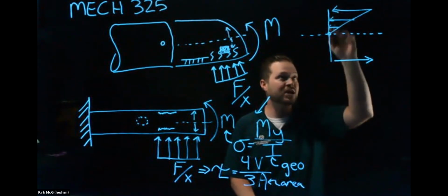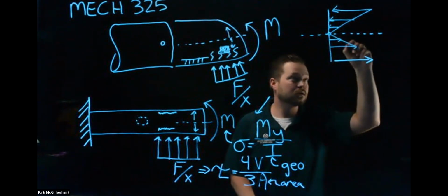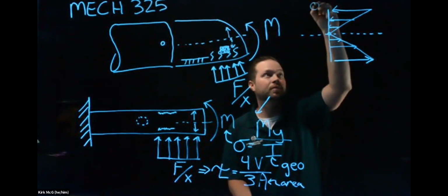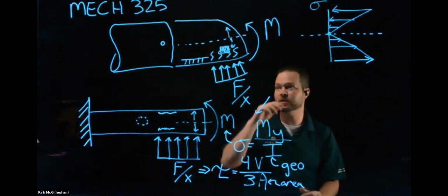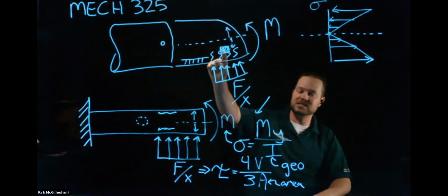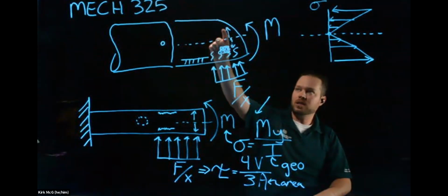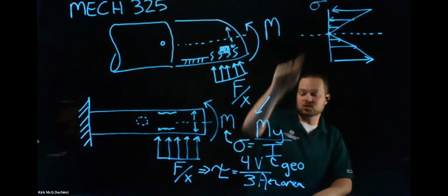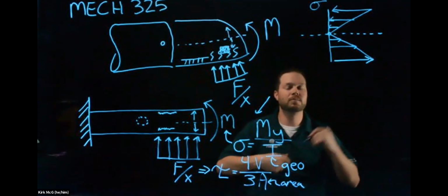So this is intense compression. And then it increases as we go away. So this is the stress distribution. So this is sigma, okay? So interesting, all of a sudden as mechanical engineers, we realize that if I'm doing design of where I want to place my sensor, it matters if I put it on the tip, in the middle, on the top, due to this force, okay? This stress is also a function of geometry. So we have a lot of things to consider here, okay?